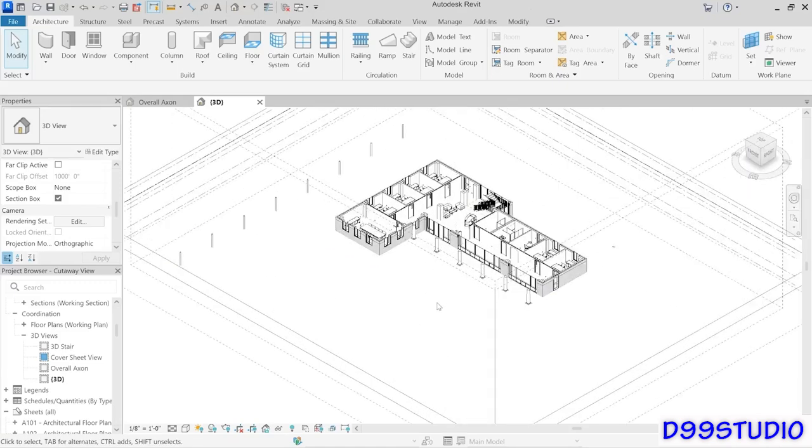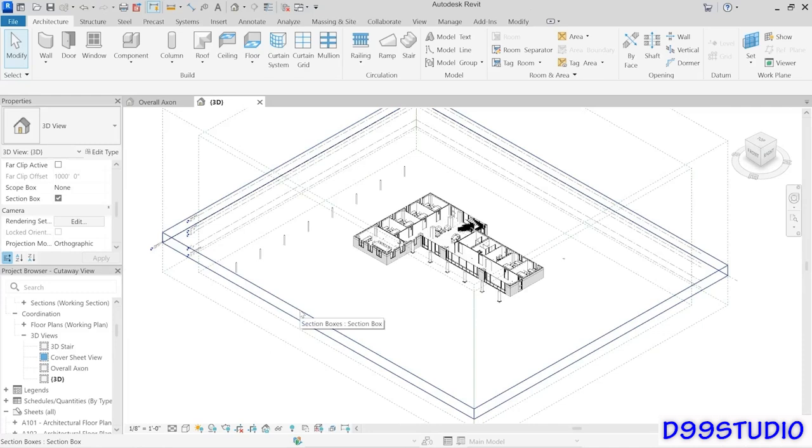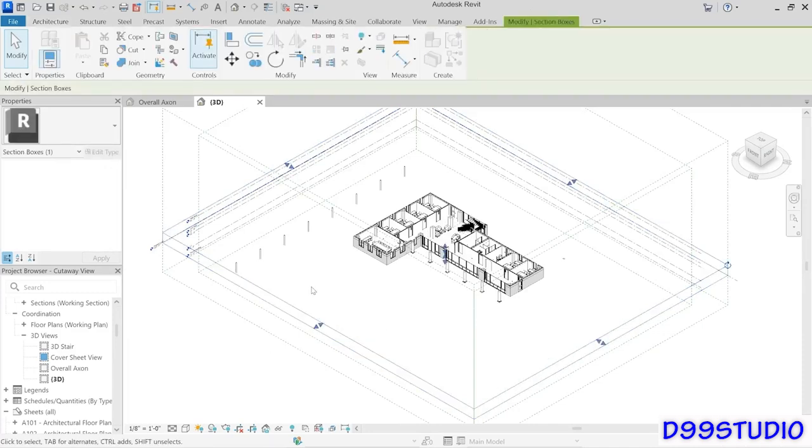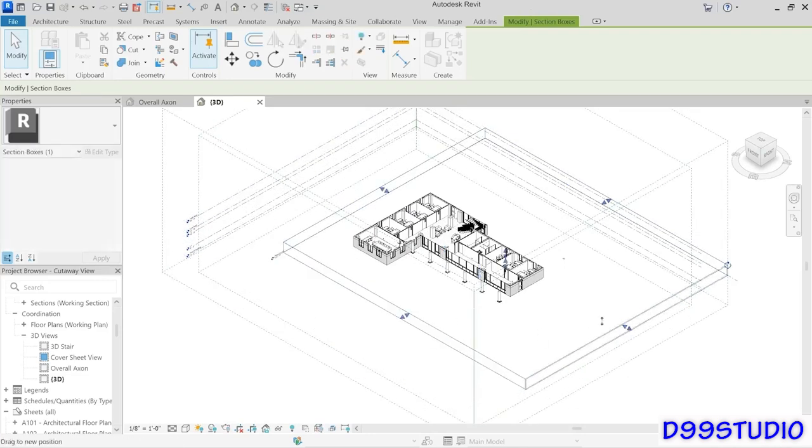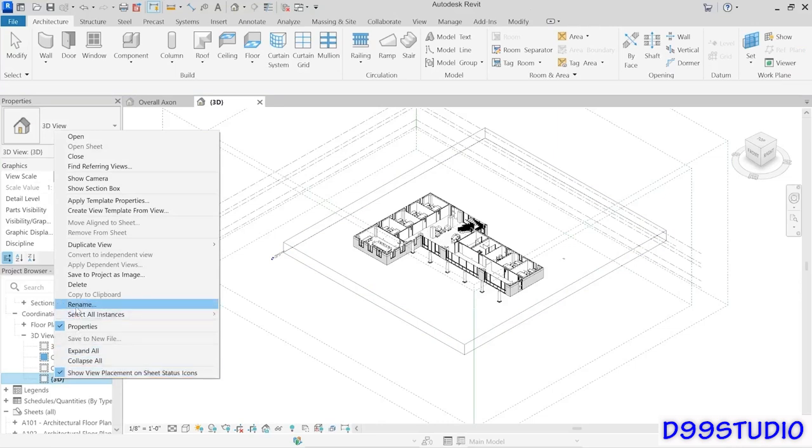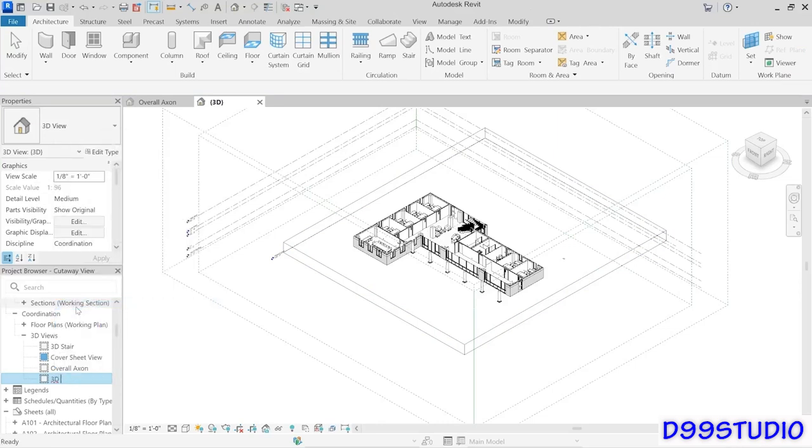And now you can see that what we've created is this little cutaway plan version of the 3D view. Now, the section box is out here, and you can just see that it's really long and thin, but you've got the little grips, and you could maybe crop out those windmills or crop out any other geometry out in the site that you weren't interested in. So you can certainly fine tune it after you've oriented it to the view, but Orient to View is a good start to kind of get you close to what you're looking for. Now, just like we did before, it's a pretty good idea to get in the habit of renaming this. So I'm going to call this one 3D First Floor.